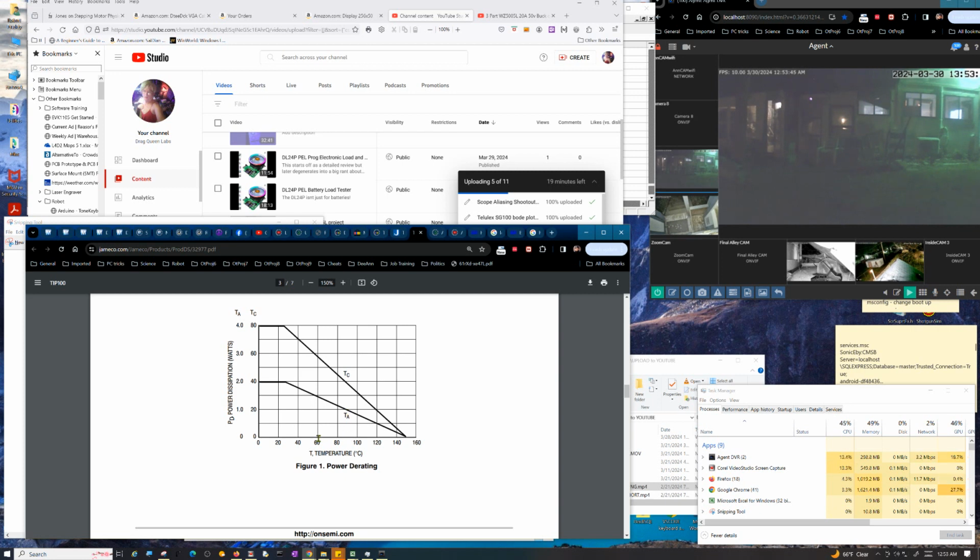And if you're operating at, let's say, 60 degrees, if that's what you measure or expect to be in your environment in that area, then okay, you'd have that 62.5 degree rise above 60 degrees, so it would be 123 degrees. It would put it here, but that's still well below our TJ max, which is 150. Now if you use heat sinks on it, you can get much better performance here.